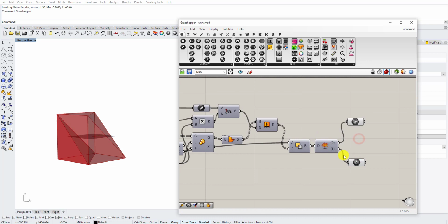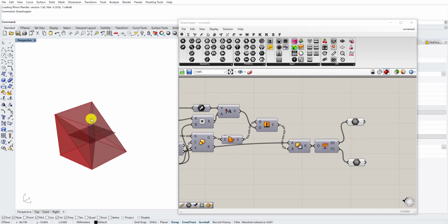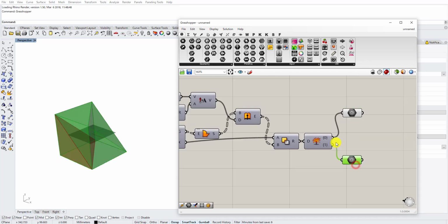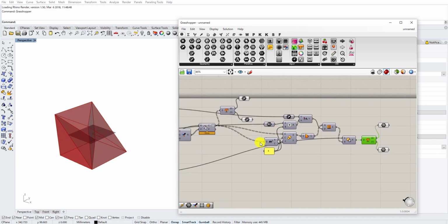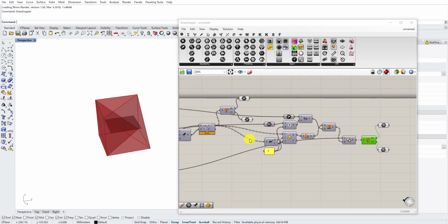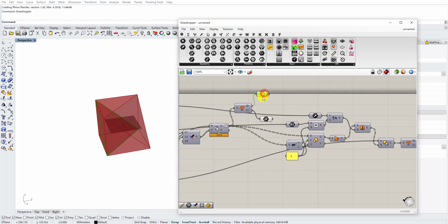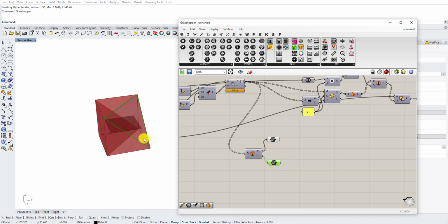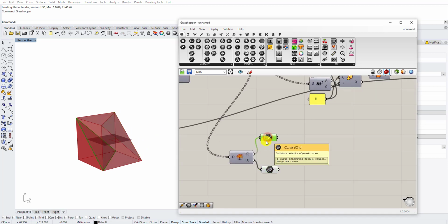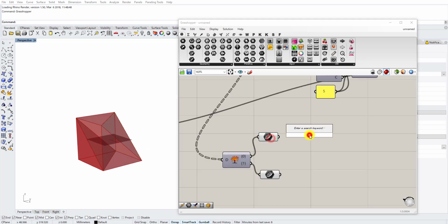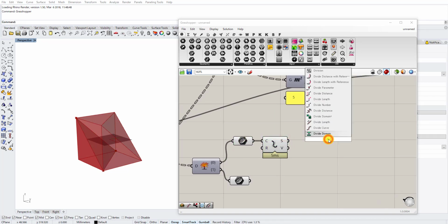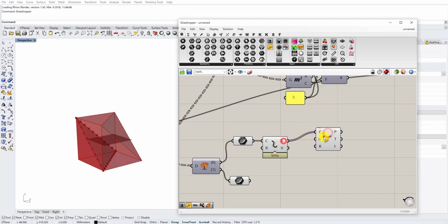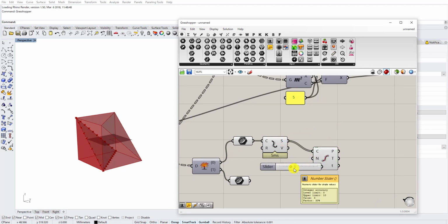Okay, what I want to do is to get a geometry here intersected with this one, so let's make that. First of all, from the bottom curve, I can bring this here. What I can do is simply explode this bottom curve and divide each line with a division of 3.